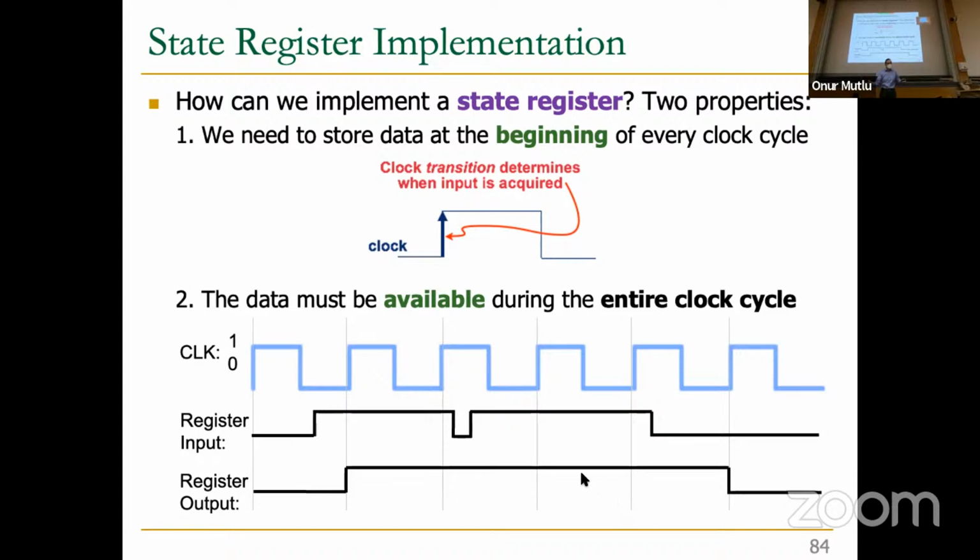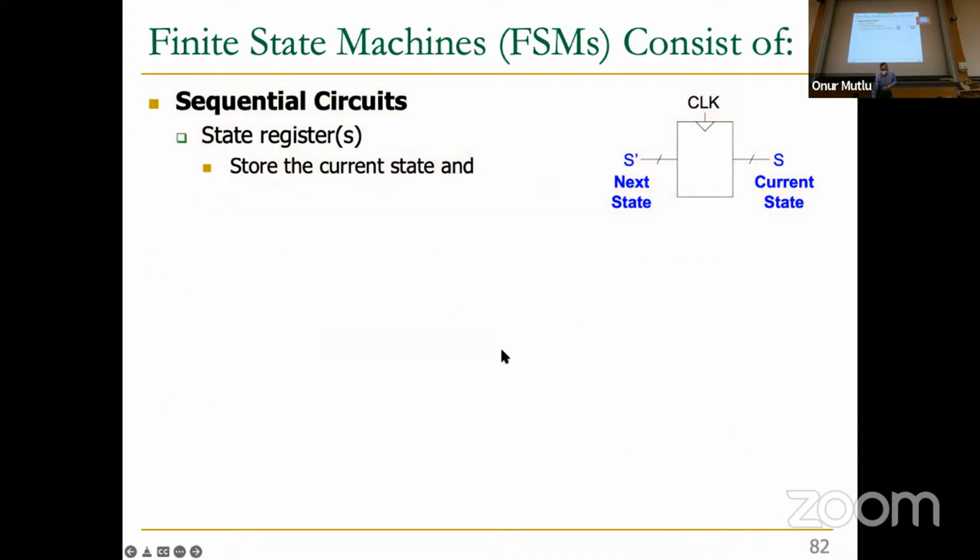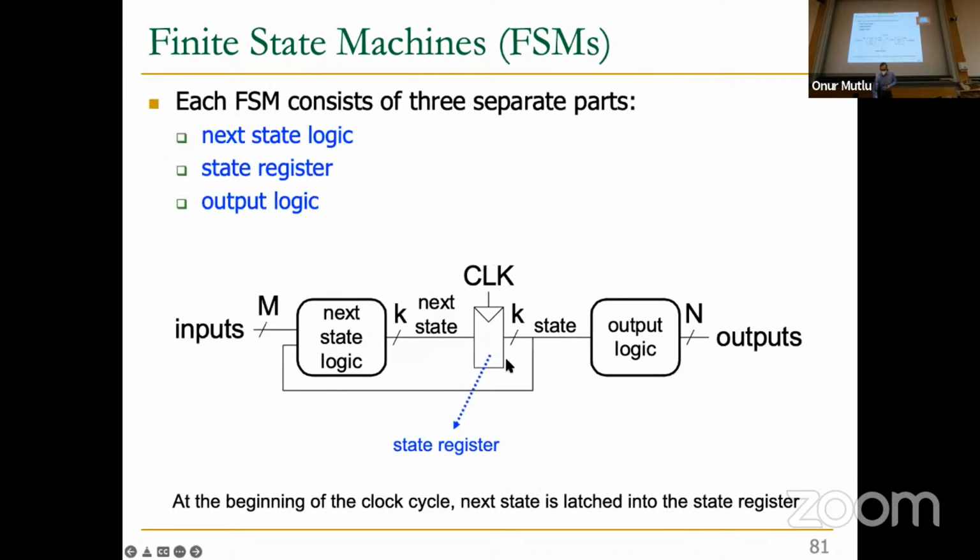And why did we set that principle? Because there's a reason why we want to stay long enough in the state: there's some combinational logic that's evaluating. And if you capture some state earlier, that combinational logic depends on the prior state that was stored, or current state, and you're changing the current state while the combinational logic is evaluating. So if you go back over here, well, actually here. Yeah, this is what the state looks like. So state, there's some combinational logic.